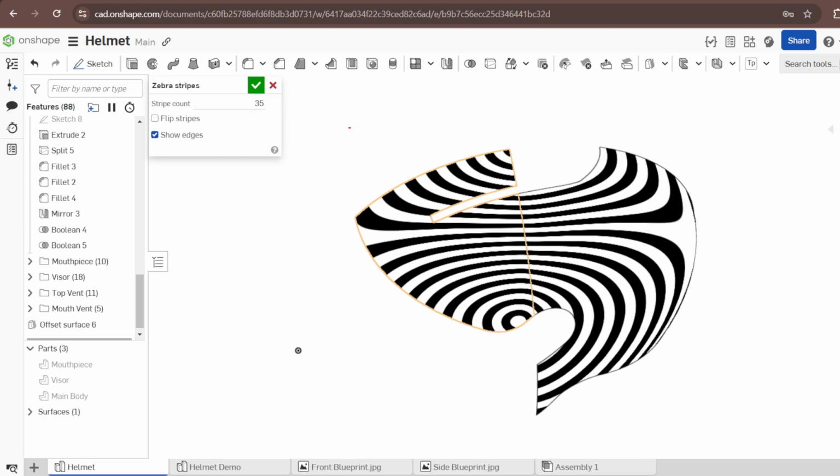We usually have G0 continuity, whereby two surfaces meet but they are not tangent. G1 is whereby two surfaces meet and are connected to each other using tangency. Okay, G2 continuity, let me draw it here.